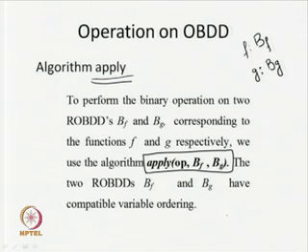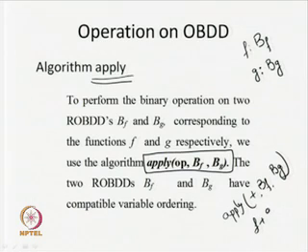Now, if I use this particular function apply, say plus BF BG, in this particular case what will happen? We are going to perform the OR operation on Boolean functions f and g. So, f plus g, and after that we are going to represent these with our BDDs or ROBDDs. So, we have the BDD representation of Boolean function f and the BDD representation of g.